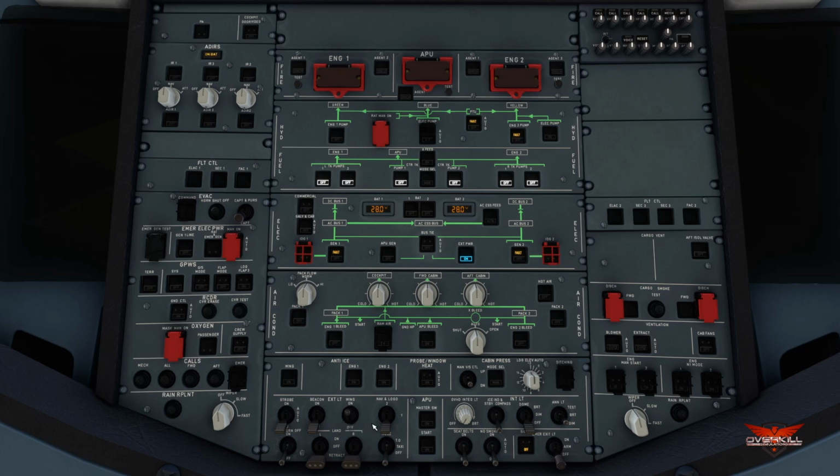And we're going to turn on our crew oxygen supply. Wing lights and nav logo lights come on. No smoking, no portable devices come on. Seatbelt signs remain off until the aircraft is fueled. Emergency exit lights are now armed. Fuel pumps will also remain off until the aircraft is fueled, as well as the APU. So we will not be doing the APU fire test just yet.